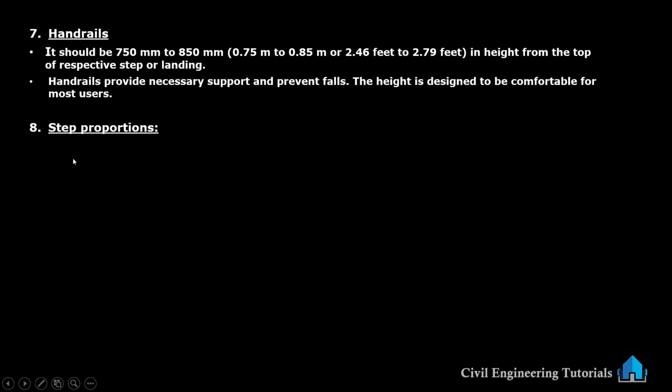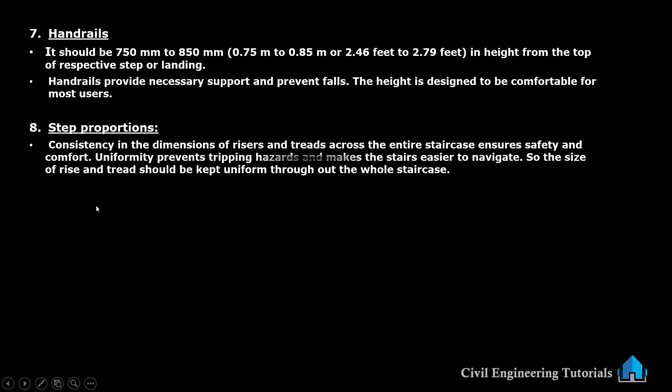Next, step proportions. Consistency in the dimensions of risers and treads across the entire staircase ensures safety and comfort. Uniformity prevents tripping hazards and makes the stair easier to navigate. So the size of rise and tread should be kept uniform throughout the whole staircase.